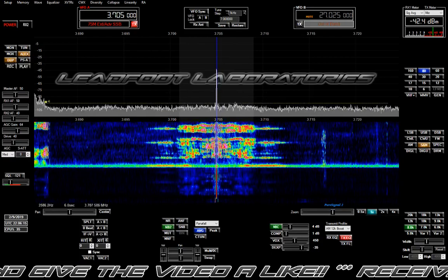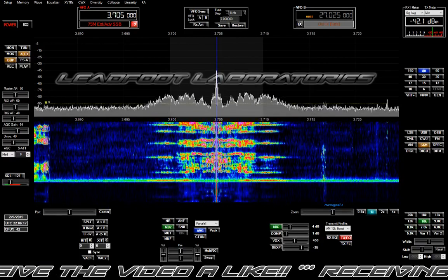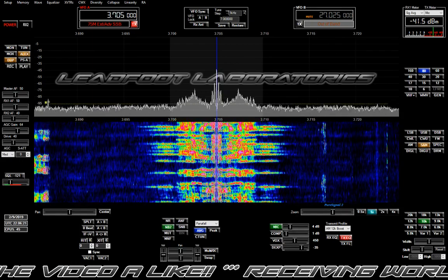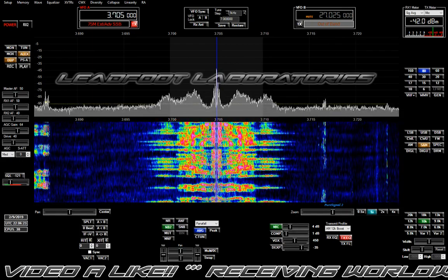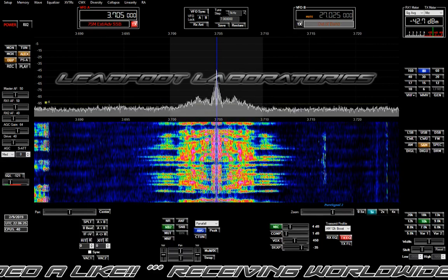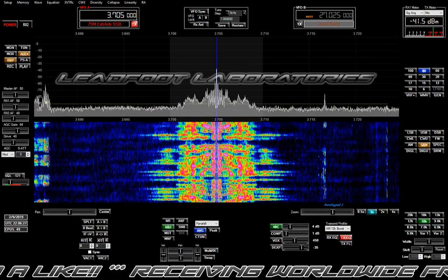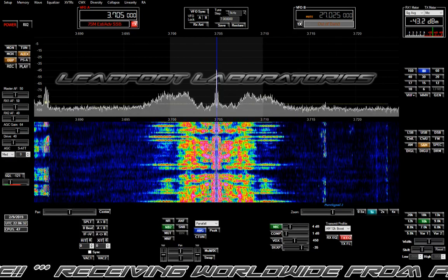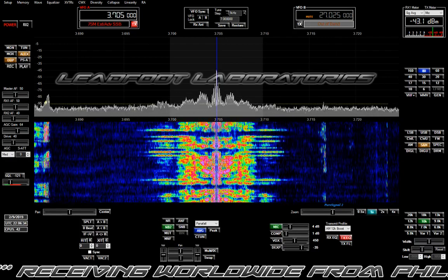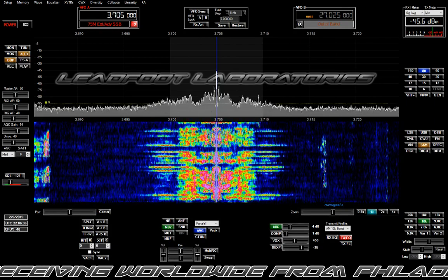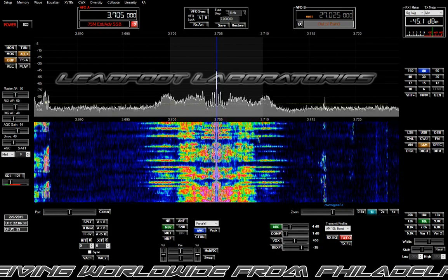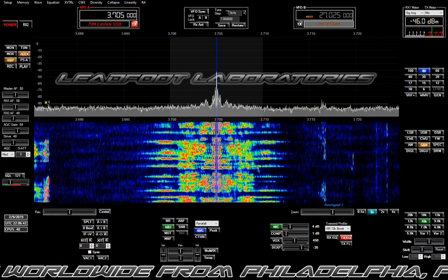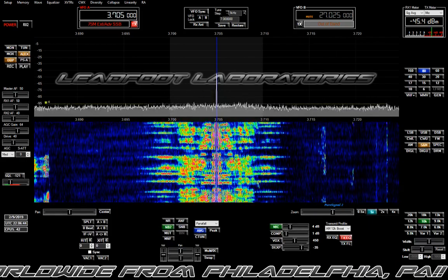On your SDR, I'm just wondering what you're seeing as far as the transmitted bandwidth, because I said to this fella by email, if it was really a problem, you should have dropped down to the frequency, let me know, and I would have cut back on the high frequency boost, because I really do boost the highs. I'm a strong believer, like we were talking last week, that once my signal takes a trip through the other guy's receiver, that's where really a lot of the brilliance in the audio is lost.